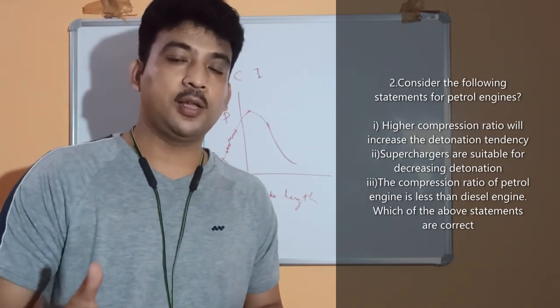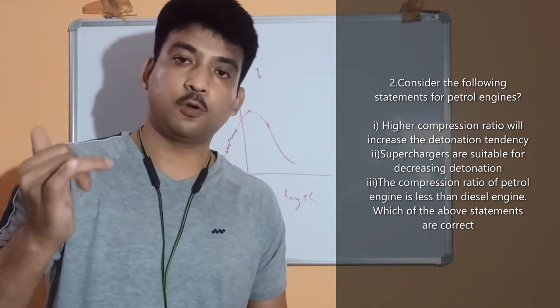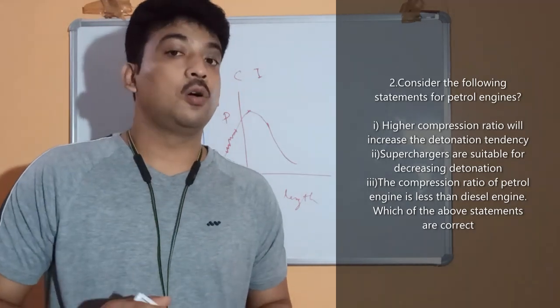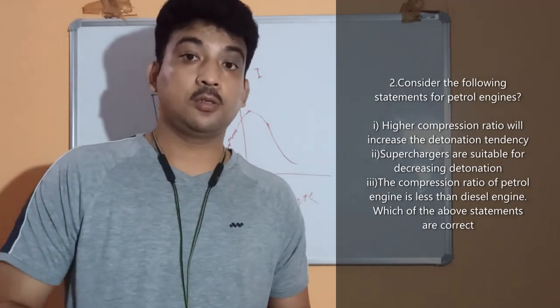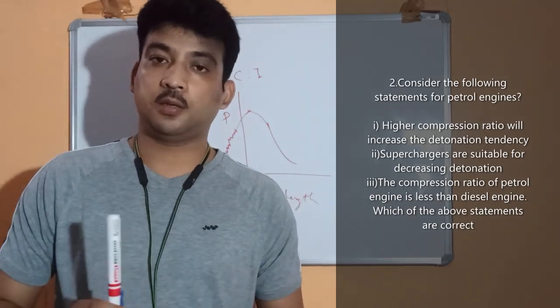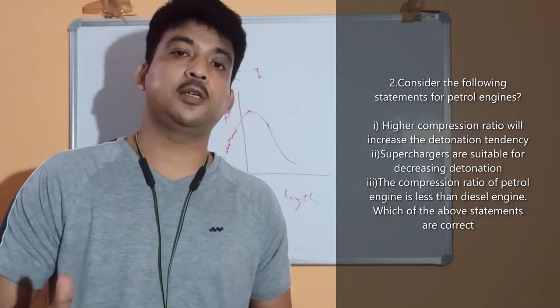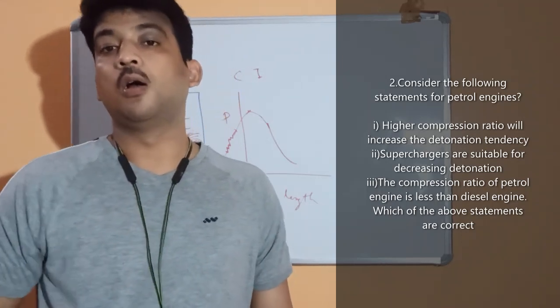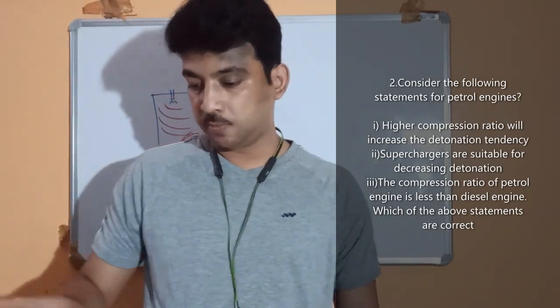And as I told you, in case of a petrol engine, if pressure is more, then the chance of occurrence of knocking is also more. So the second statement here is not correct, because supercharging will increase pressure and that will also increase the tendency of knocking or detonation. The second statement is wrong.